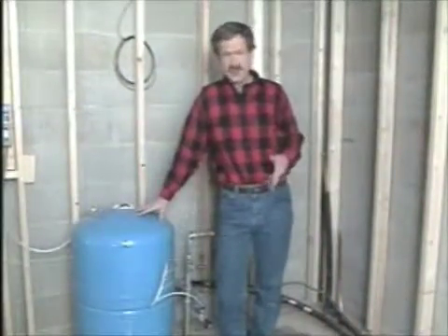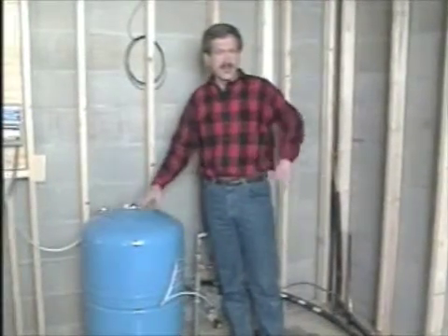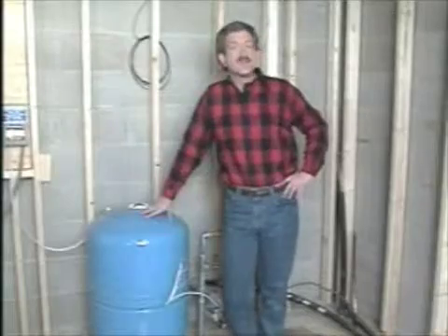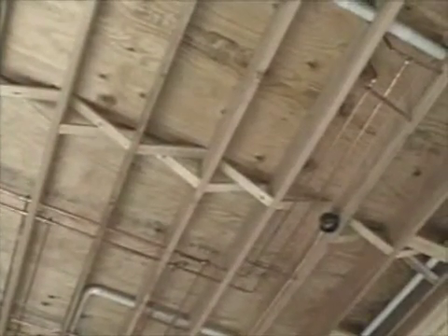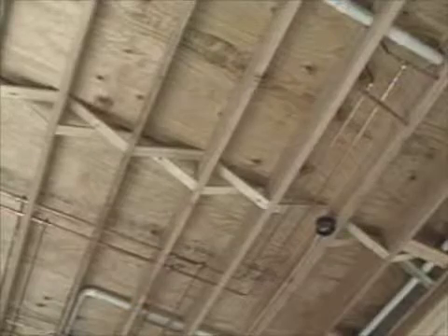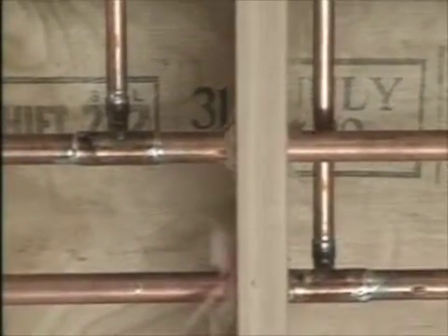In this home, it originates in a private well. It's pumped into this pressure tank, and once it's hooked up, it'll be distributed throughout the house in lines quite a bit smaller than the DWV lines. Most of the supply lines have been laid out upstairs. They're made of copper, with the main runs 3/4 of an inch in diameter, and the branch runs 1/2 inch in diameter. Like the DWV pipes, the water mains branch off to service several fixtures.